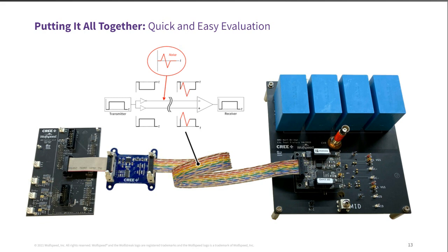And then it's always necessary for safety, or if it's in an enclosure, or just based on where the scope is or the test bay, that the differential signaling might need to be a little bit longer. But that's what the differential transceiver tool is for, to provide that differential signaling to help prevent any issues from noise coupling in.